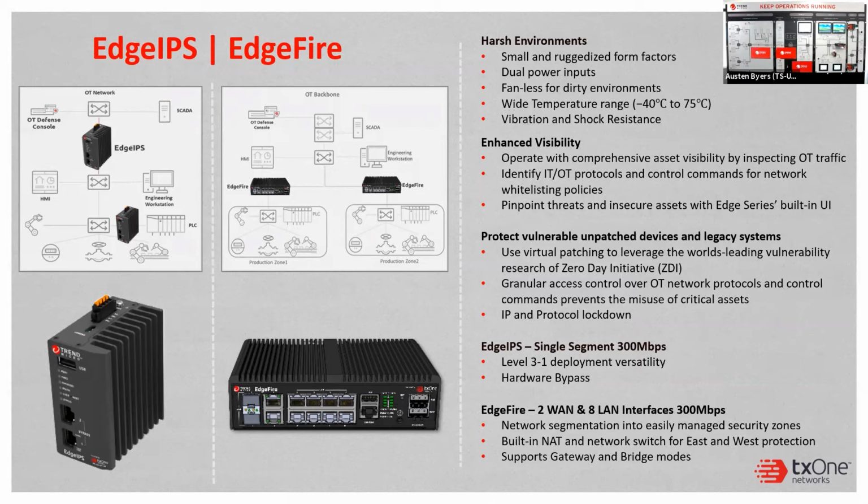So we can dive down into the system commands and the actual system code of the OT protocols, specifically like, say, Modbus, that is very prevalent with PLCs. We can say who has read and write privileges. We can say what PLC or what machines can have the ability to send commands to these machines, and what commands they're able to do. So this helps to prevent against harmful commands that aren't necessarily malicious, which is very prevalent within OT.